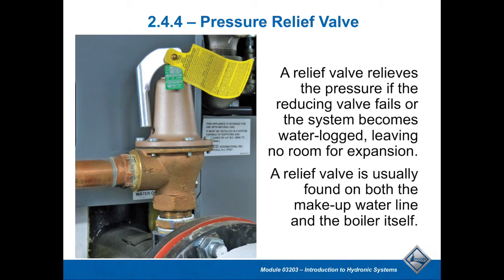The pressure relief valve has a job, and its job is really intended as that boiler warms up and that water expands. If there's any situation where the pressure in the boiler system exceeds the pressure rating of any closed system, this valve needs to be able to relieve it and allow that water to push that little diaphragm out, let's say, and then essentially expel that water and relieve that boiler of its pressure.